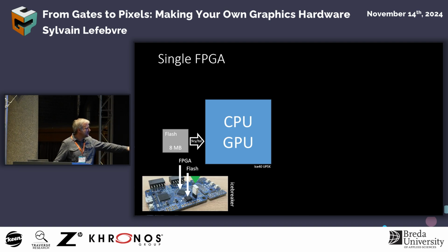And you can see it here on this iCEBreaker board, very nice board for getting started. This is the FPGA and this is the flash. The reason there's a flash is because this is where the FPGA is reading its configuration from when you boot up, when you power up the board, right? The FPGA has to be configured. This configuration is a file, so to speak, a piece of memory that is stored on this flash chip.